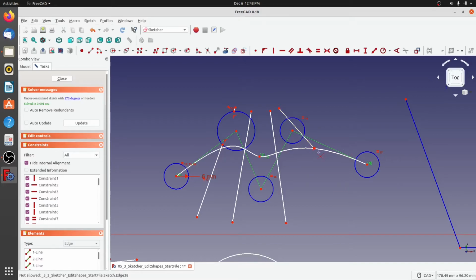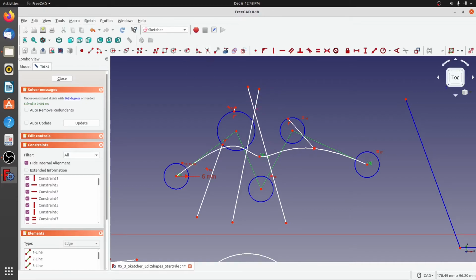So what can be trimmed up to? The edges of the trim will be either a B-spline, a construction line, or just a line segment. Just to prove my point, how about we do it this way and again. So this is just a point, 2 line segments, and trim will trim it that way. This line segment, I'm trying to trim it with the help of a construction circle, and FreeCAD does that very easily.